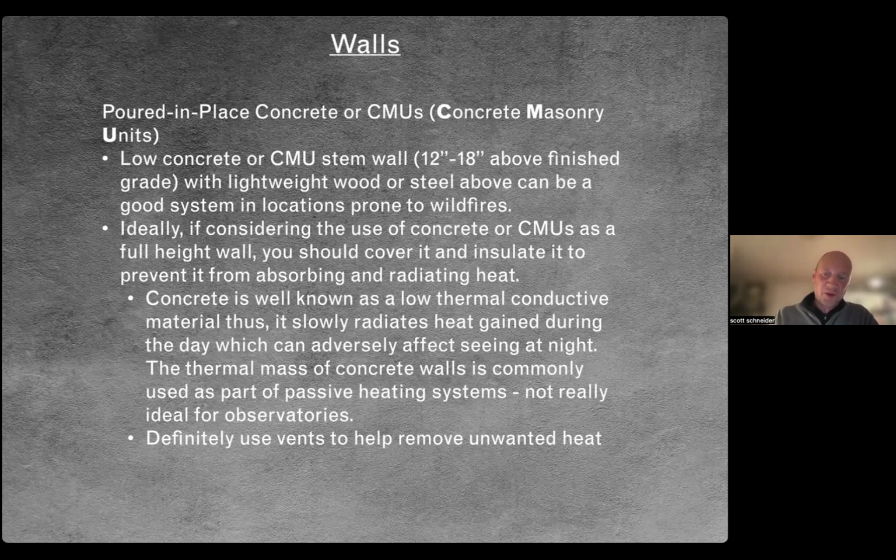So one thing you can do though, if you're concerned about fire, and this is maybe a really good thing to do if you're in an area where there's potential for wildfire, is to build a lower stem wall out of concrete. And then you put your framing on top of that so that any embers that might be blowing through the wind hit the concrete and don't burn. They don't start your structure on fire. At least there's a lot less potential for that.